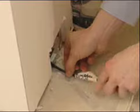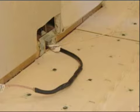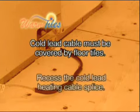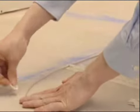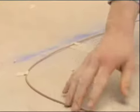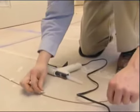Next, pull the cold lead up into the electrical box until the cold lead heating cable splice is within 6 inches of the sill plate. Position the cold lead heating cable splice so that it will be completely covered by mortar or floor tiles. Recess the cold lead heating cable splice to the same height as the copper heating cable. The concrete may need to be chiseled to a depth of 1/4 inch. The cold lead heating cable splice is fastened to the floor using the clips included with the Warm Tiles cable kit. Glue the clips into position. When routing heating cable to the beginning of the strapping, use clips to attach heating cable to the subfloor.